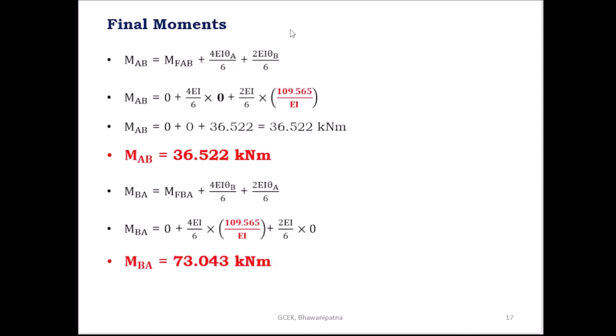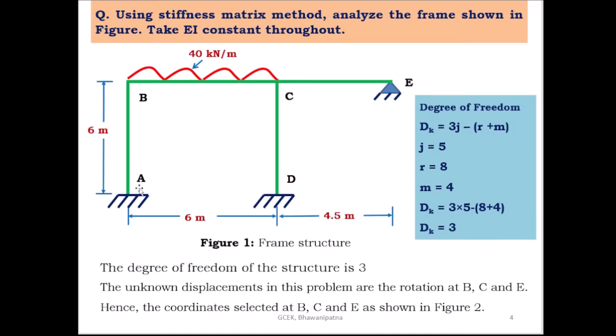So find out the final moments by using the slope deflection equations. Here you find out the final moments MAB, MBA, MBC, MCB, MCE, MEC, then MCD, then MDC.